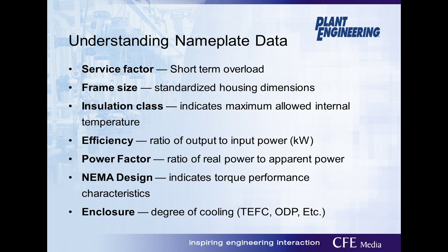As Mike talked about earlier, the insulation class indicates maximum allowed internal temperatures a motor should operate at, and these classes are based on a motor designed to operate at a 40 degrees C ambient temperature. Standard class rating for a general purpose NEMA motor is referenced usually as class F. But if you know your application is withstanding ambient temperatures above 40 degrees C on a regular basis and the motor runs at full load most of the time, it is best to order a motor with a Class H insulation. Knowing heat is the leading source of motor failures, it is always best to make sure that proper ventilation and temperature monitoring is always in place.